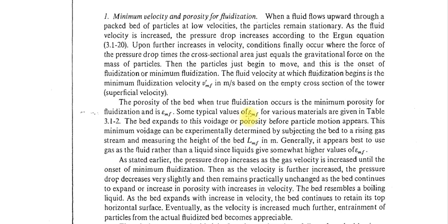It is represented by xi-mf. This is the void fraction or porosity of the bed when the fluidization starts. This is when you achieve the minimum fluidization velocity, which is represented by v dash mf. This is the superficial minimum fluidization velocity.